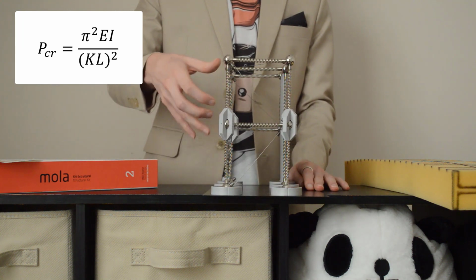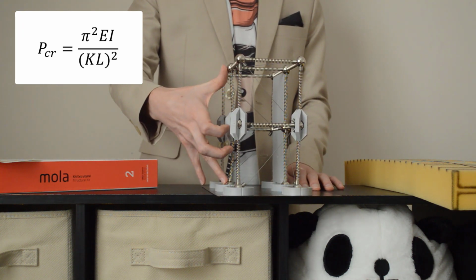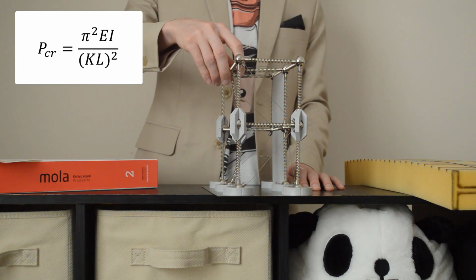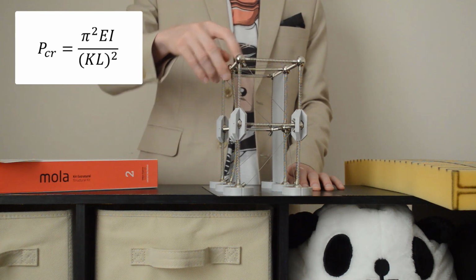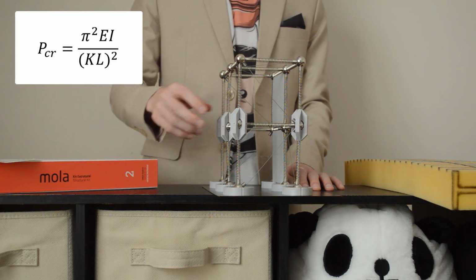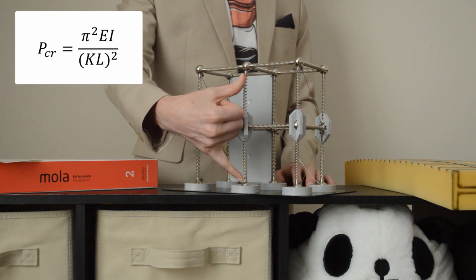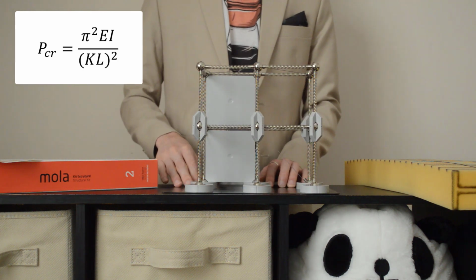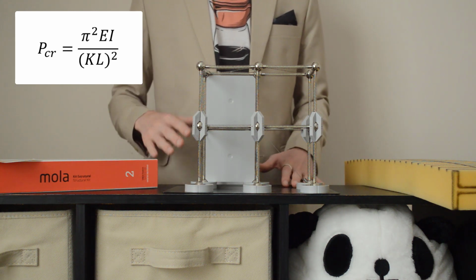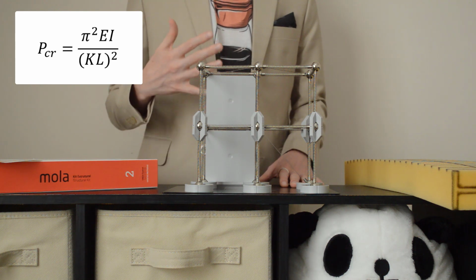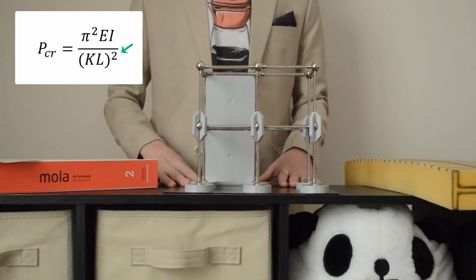However, in this direction, now its unsupported height is 2 stories, or in other words, it's been doubled. And if you pay particularly close attention to Euler's buckling formula, you'll know that when you double the unsupported length of a column, what you're really doing is cutting that capacity by 4 times, because that length is squared in the formula.